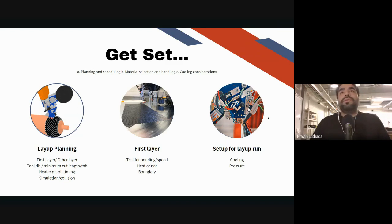And then you would want to have some sort of approach to bond the first point, or staple the first point and the end point. So that can be achieved either by putting just the same thermoplastic strip, a UD tape, perpendicular to the direction of the layup at the beginning and at the end point, and you just put a double-sided tape under it or something like that, and then you start. Because now at the beginning point there is the thermoplastic strip, and at the end point you're able to get some sort of starting and ending, and it starts to hold well.